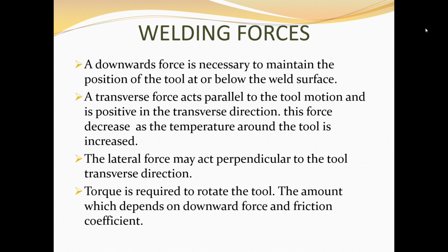Next, coming to the welding forces. A downwards force is necessary to maintain the position of the tool at or below the weld surface. A transverse force acts parallel to the tool motion and is positive in the transverse direction. This force decreases as temperature around the tool is increased. The lateral force may act perpendicular to the tool transverse direction. Torque is required to rotate the tool, the amount of which depends on the downward force and the friction coefficient.